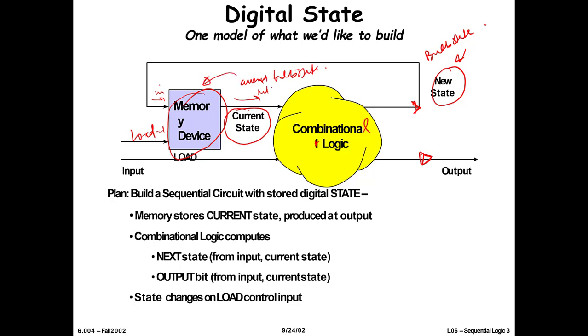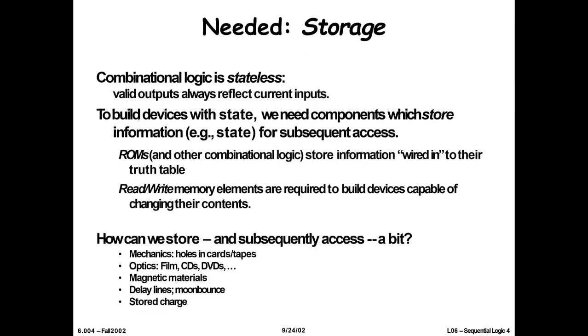So previously, if the bulb is off, this will be off. And when you combine this with the current input, so if the current input is a push of the button, then your next state will become on, which is again stored in the memory device for the next cycle. So you see there is a feedback. Okay, so this is a model for our sequential logic.